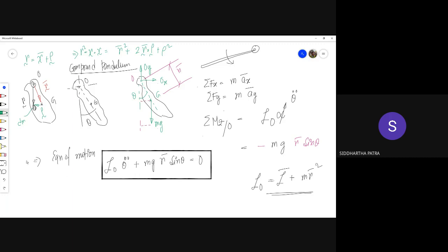So when I integrate this quantity to get the mass moment of inertia about O, that becomes, first of all, R bar squared integration dm, plus the third term, which is integration rho squared dm, and then this term right here. You see, this R bar is a constant.